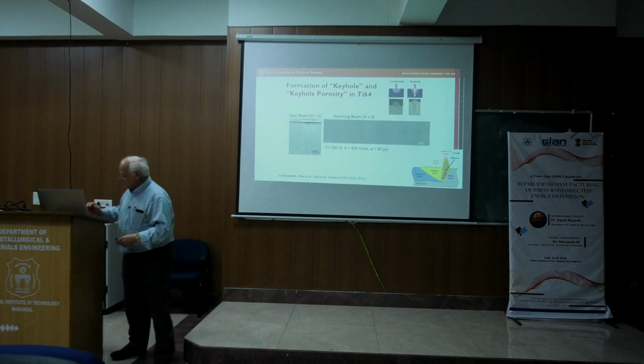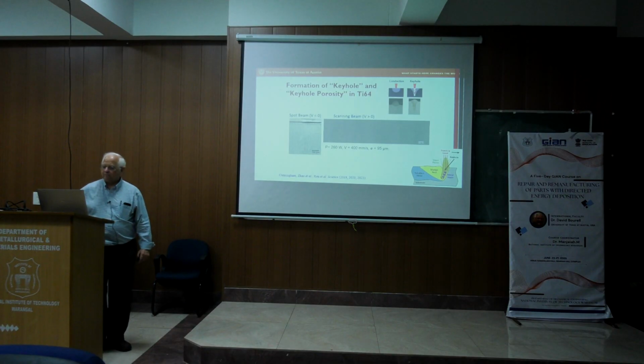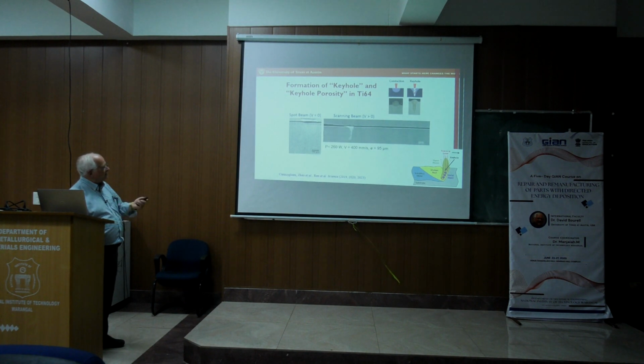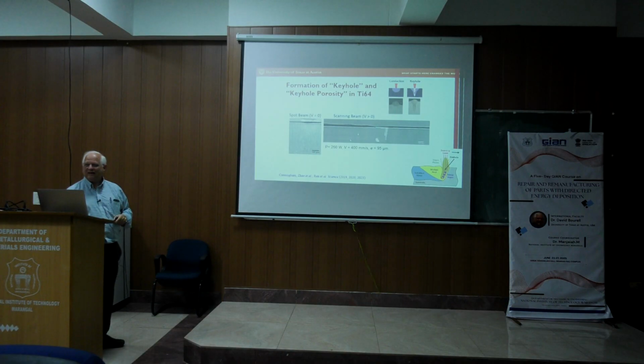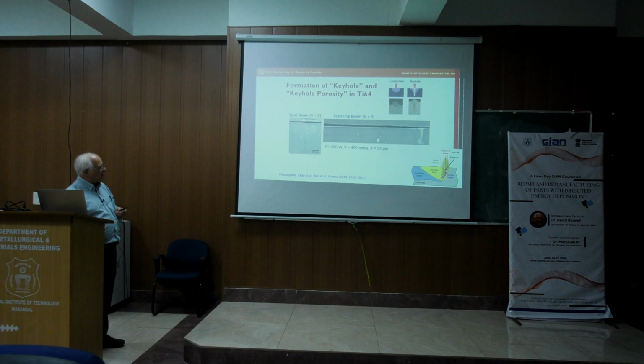So let me show you this. It's actually, I think, a fairly dramatic video here. So let's take a look at this. So here comes the laser. In this case, the light is actually the keyhole. So you see how it blocks off the porosity here, which is the source of the keyhole porosity.